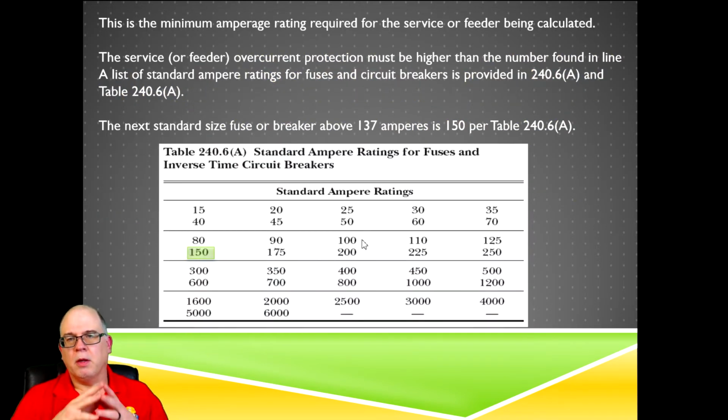Now, what do we have to do? I need to decide. I know what my load is, my calculated load. Don't lose sight of that term, calculated load. Connected load is before we did anything, when we took all those values. We're now at a calculated load. We've done some calcs, we've applied some demands. Now we have to size the breaker.